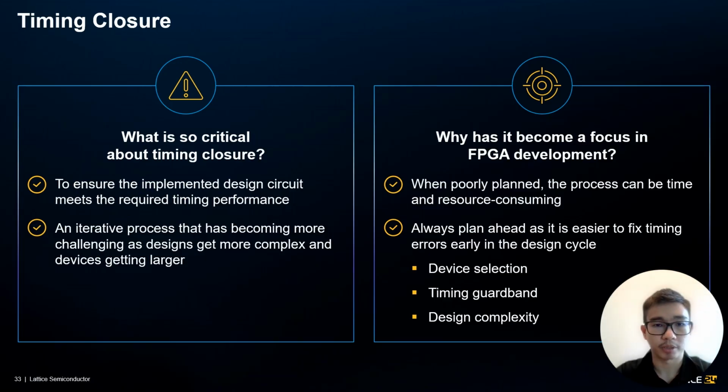Timing closure is important because it ensures that our designs meet the required timing performance and at the same time function correctly as intended. This process has become more and more challenging as designs grow in complexity and sizes, often resulting in multiple iterations. It has become more relevant in FPGA development because when not planned, the process will become more time and resource consuming. Hence, it is always advisable to plan ahead in the early phase of the design cycle.